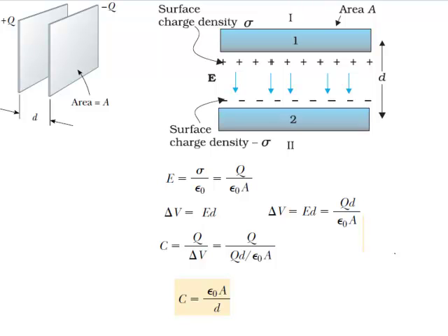Second thing is to decrease the distance. When we decrease the distance beyond a certain level, we might have a stronger electrical field which might leak the charge. So D also has certain limitations from the point of view of dielectric field strength. So we have to maintain a relation between A and D such that neither of these two challenges leads to a breakdown of the dielectric.